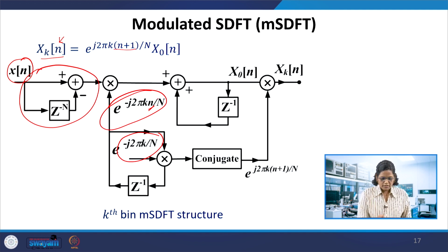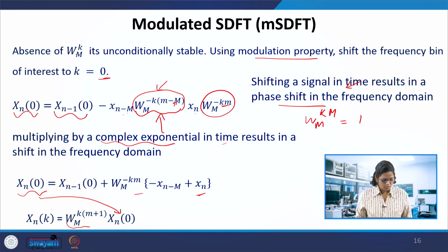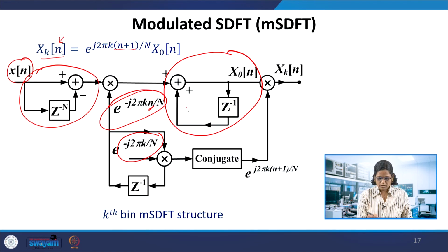So this is an instantaneous signal cos 2πkn/N minus j sin 2πkn/N, but this is a constant e^(-j2πkn/N). So it is delayed over here, and this is the part in which this x of n, that is the kth bin, 0th bin, is delayed to accumulate. If you take the z-transform of it, it will be z^-1 into x sub 0. So that's the outcome of this particular integrator.